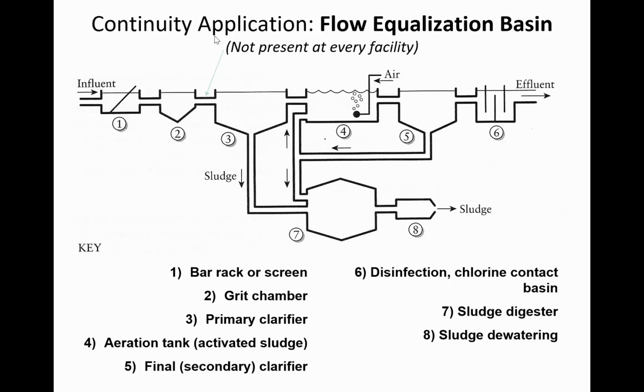So what we do to treat the wastewater is we have this aeration basin at a treatment plant where they pump in, using blowers and diffusing stones, a lot of air and try to burn up all of that desire for oxygen in the treatment plant, so that when the water is discharged to the receiving body, whether it's a lake or a stream or a river or whatever, it no longer needs any more oxygen.